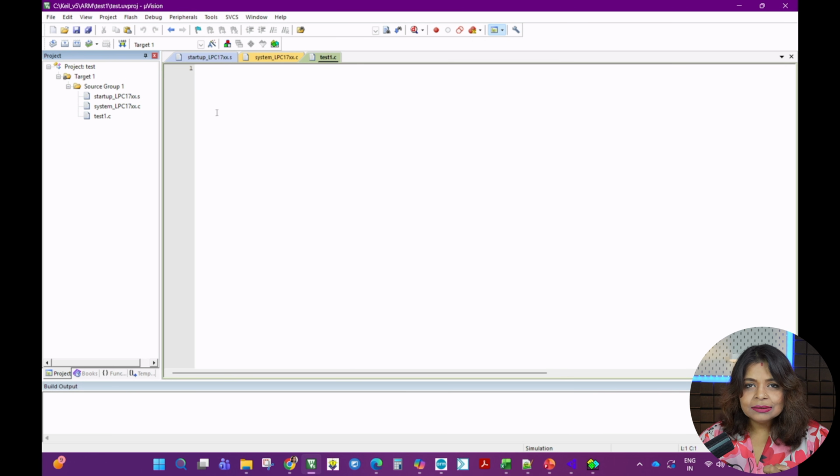So how can it be done? I have discussed in the previous video, it is through registers. Registers are nothing but a set of registers associated with each peripheral, which the developers can use to develop the code. So suppose I have selected 1768. I don't know which specific header file has that option. So what is a header file? This header file will have all the register definitions which are required to be accessed by the user while developing the code for programming the peripherals.